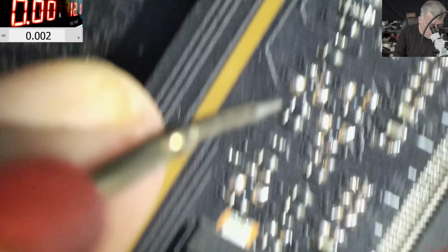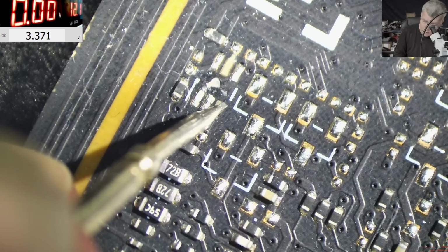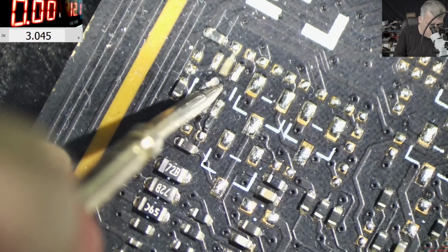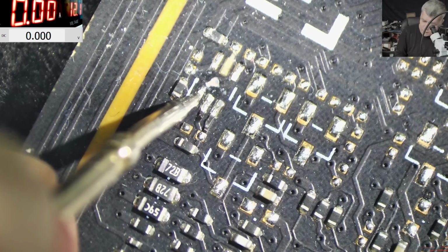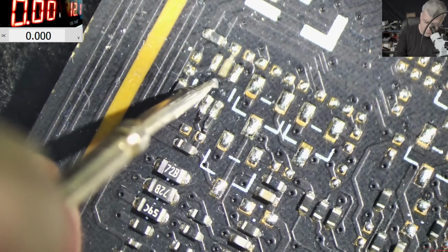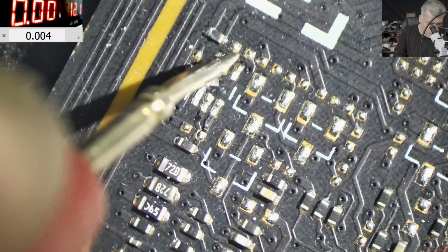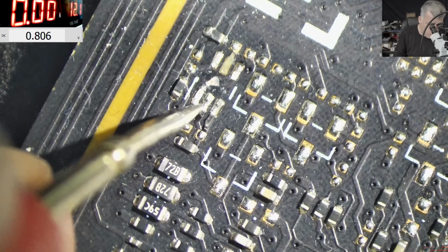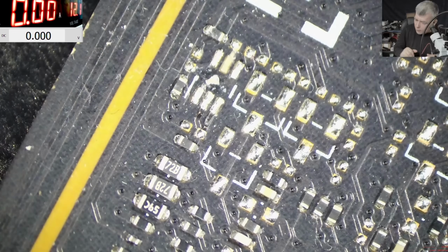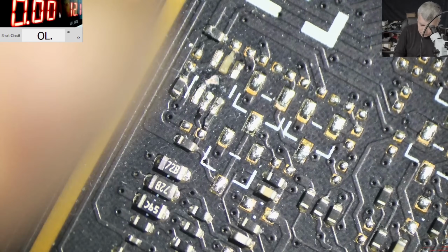Okay. So what do we have on this missing component? Here we have 3.3. So you see this component is active even when the motherboard is off. Here we have 3.3. Here we have nothing. Here we have nothing. Here we have 3.3. So 3.3 here, 3.3 here, 3.3 here. I want to know the other pins, what they are doing, just to understand what this component is doing.